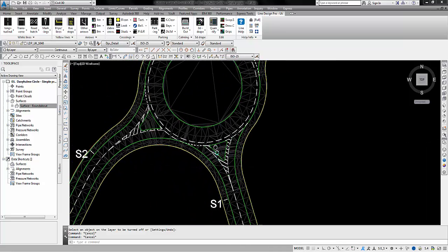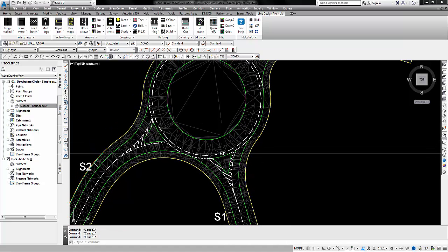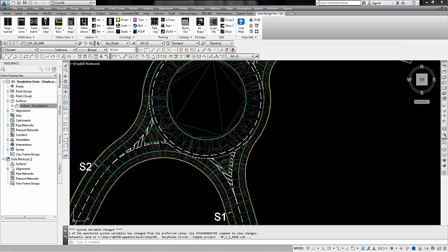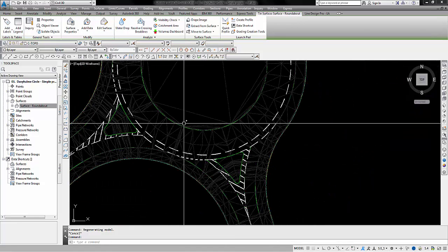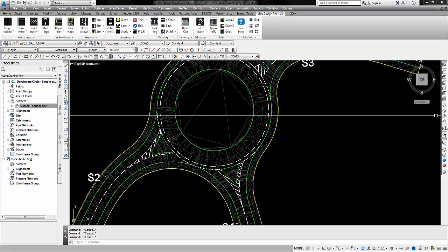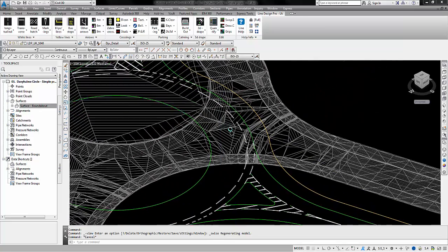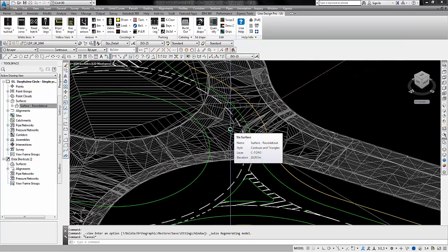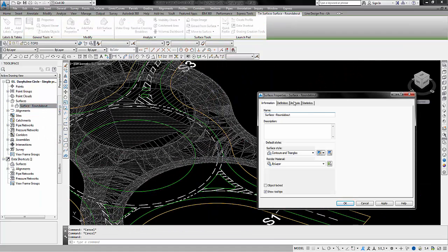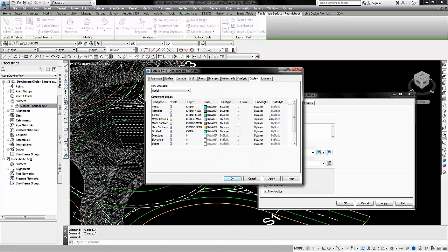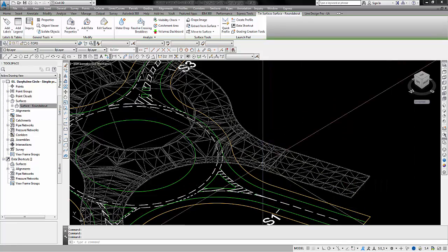Now the next thing obviously is we want the 3D road markings to be added to our design. If you can see in the background here, we've got a TIN surface because obviously we're in Civil 3D. If I just change the view to 45 degrees, you can see that there's not actually any markings on that surface at the moment. In fact, I'll just turn off the contours, major, minor, off. There we go. It's a little easier to see now.